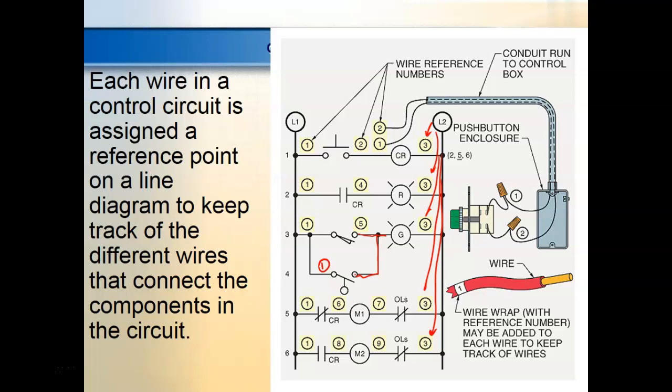Manufacturer numbers, terminal numbers that we looked at. We've already talked about a little bit over here. So when you buy a part, it's usually going to have numbers on it. And the problem is just about every one of them is going to have the number 1 on it. So when you hook up your wires, you're not looking for number 1. You're looking for the number 1 on the component you're supposed to be looking for, right?